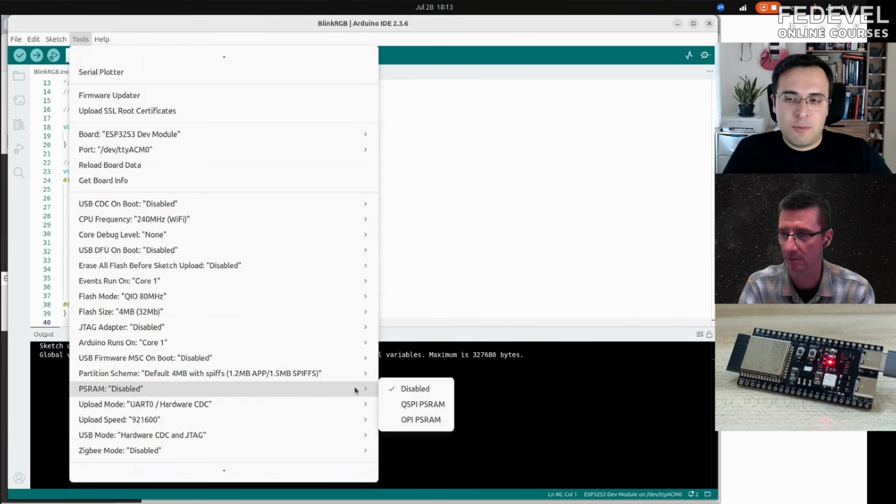But you need to design the software in a way that it can use this memory efficiently. This is a kind of advanced topic, but ESP-IDF lets you decide how to use the different RAM sections of the memory address you have for different applications, like managing the heap and stack in your software.